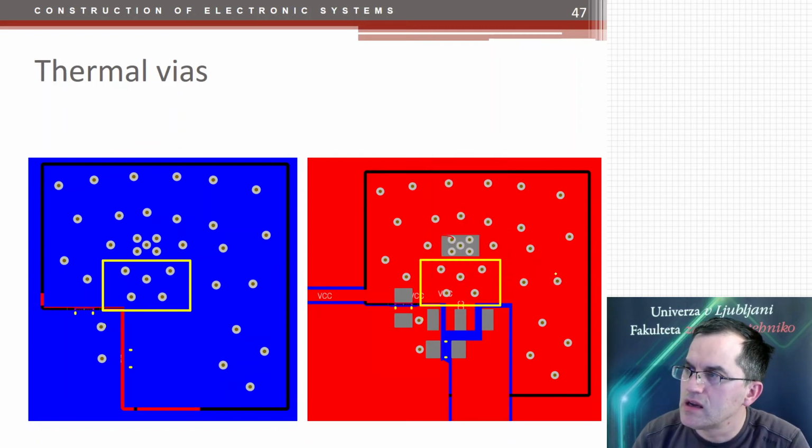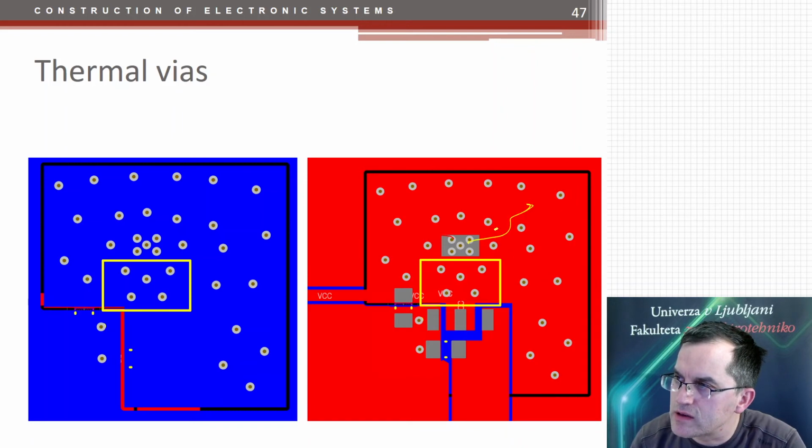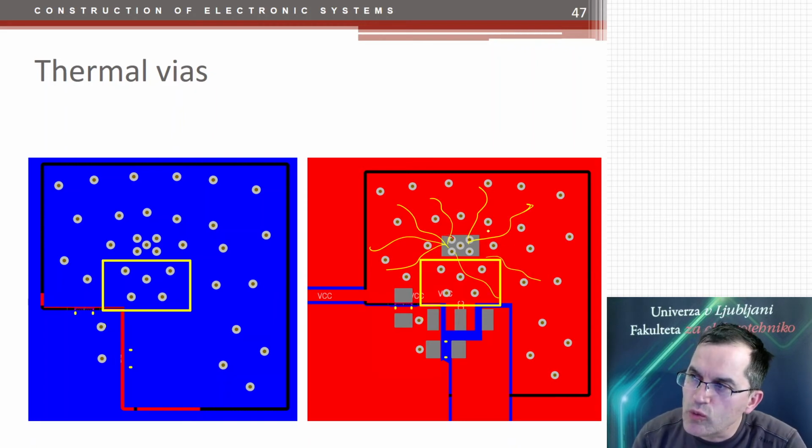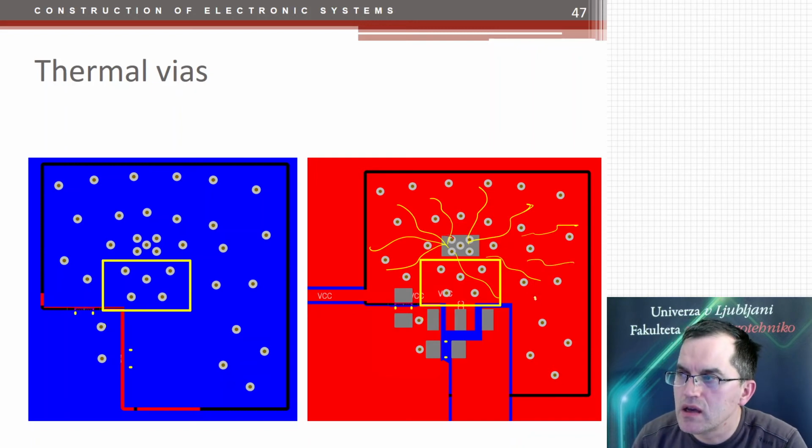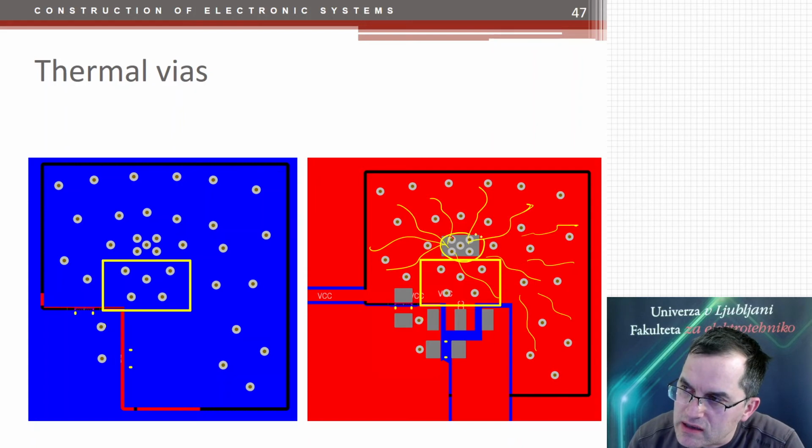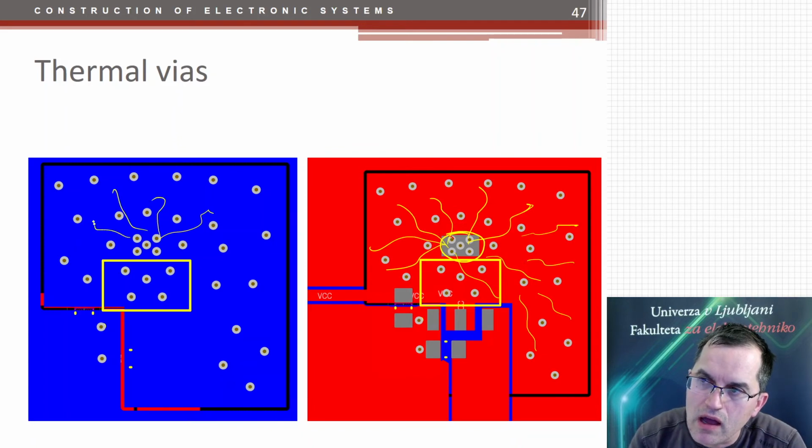So now you see here the heat has to transfer only laterally through these areas. And you don't want to put a lot of holes around it because the air inside these holes is not a good conductor. You need to leave space around so that the heat can transfer. But here it's the most important to be transferred to the bottom side, and here it could then get transferred laterally as well on the bottom layer.